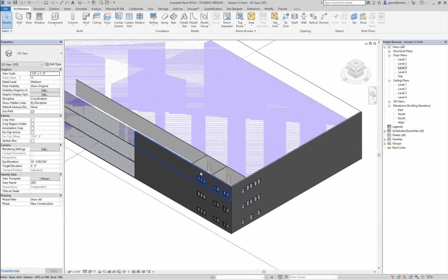Often, many types of walls we just do level to level. Curtain walls are one that often they just do the whole facade at the same time. Is it because of the intersection of the floor to the wall? It's because later when we try to use the model as a building tool, they wouldn't insert all the floor walls on all levels at the same time. They would do it level at a time.